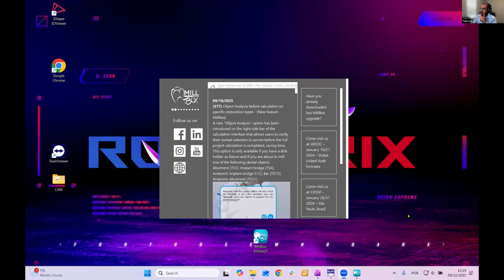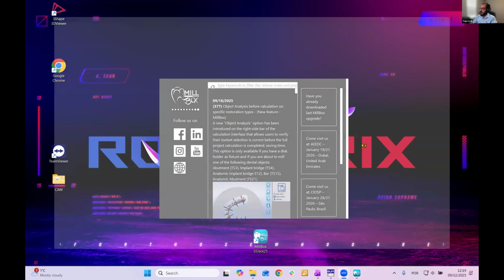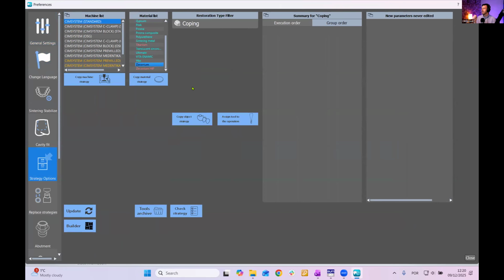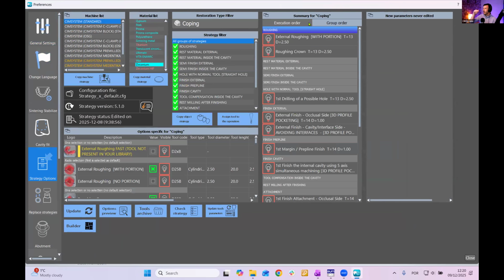Yeah, so the strategy is basically exactly what you'll be using in order to produce your parts, like your STL files. It will dictate all of the operations that we are going to apply in order to produce the part that you have. I believe that's better, right? Yeah. So each part of the strategy would be like roughing. It's the way the tool is moving through and spinning and cutting through the material. What does the tool path look like when you actually visualize it?